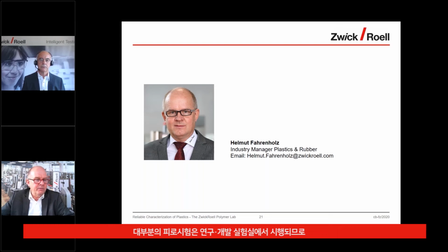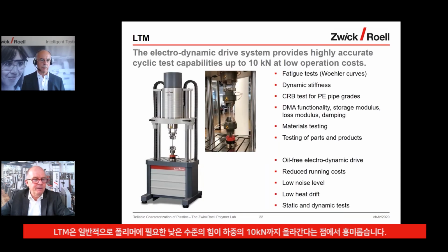So we develop and produce servo-hydraulic testing machines as well as the LTM, which is an electrodynamic testing machine. So I show you the LTM, which is interesting for, let's say, the low force level, which is typically needed for polymers. It goes up to 10 kilonewton of load, and it works with an electromechanical drive that you see here on the top of the machine. And this drive system produces oscillation frequencies of up to 100 hertz.